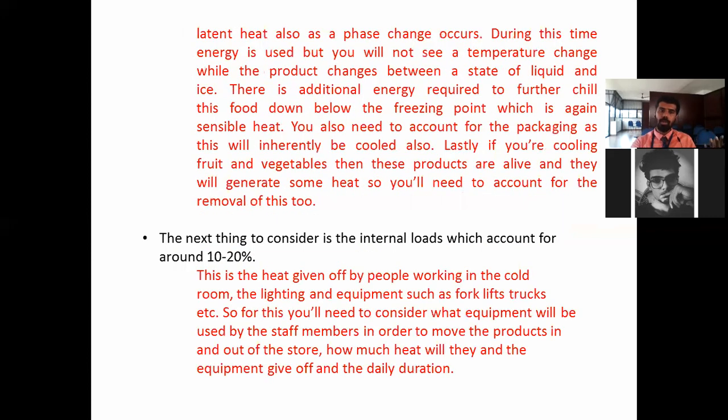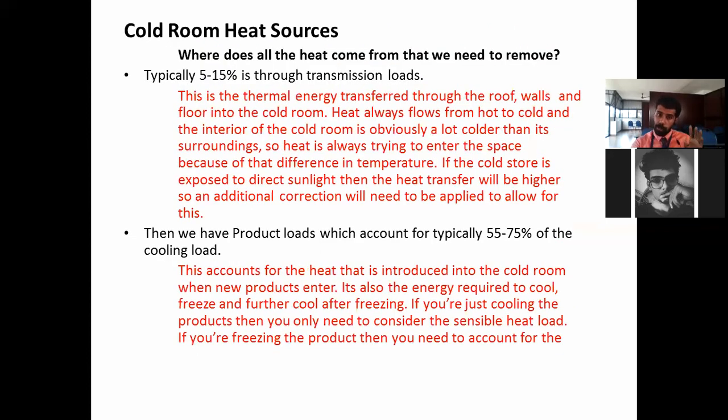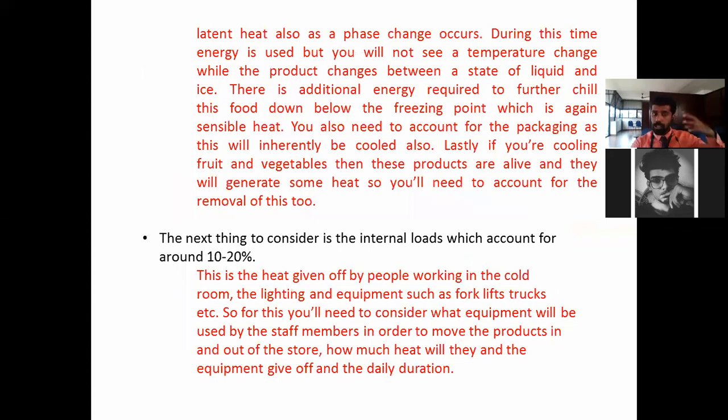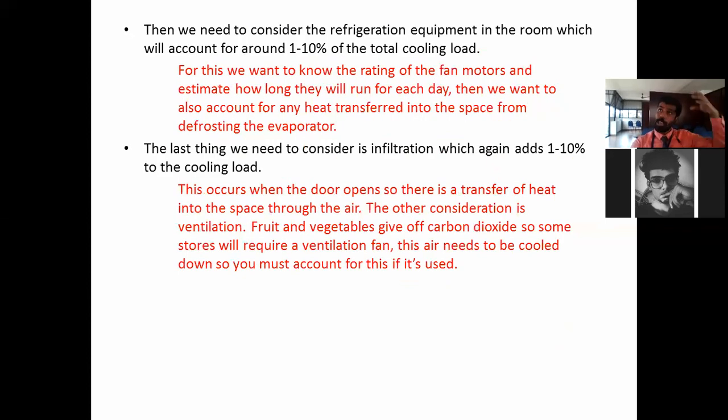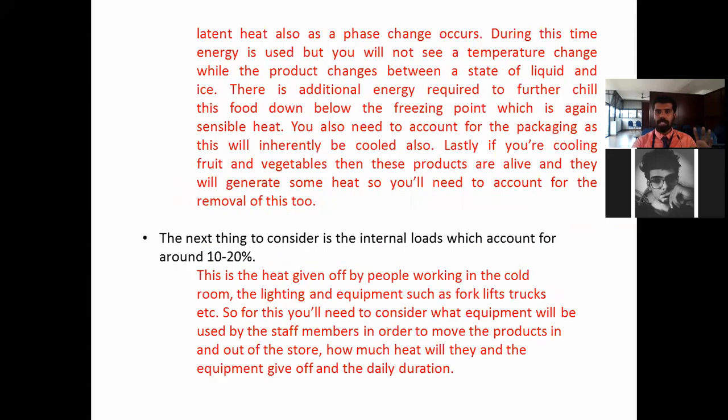Okay, so the transmission load is 5 to 15%, the product load is 55 to 75% of the cooling load, then the internal load is 10 to 20%, then the actual refrigeration equipment load is 1 to 10%, then infiltration and ventilation 1 to 10%. So these are the things that we have to consider.